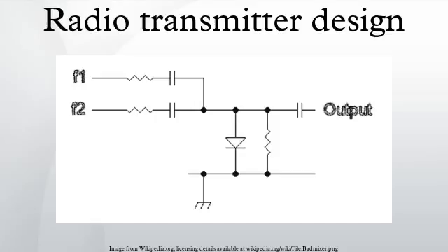Digital modes. Transmission of digital data is becoming more and more important. Digital information can be transmitted by AM and FM modulation, but often digital modulation consists of complex forms of modulation using aspects of both AM and FM. COFDM is used for DRM broadcasts. The transmitted signal consists of multiple carriers each modulated in both amplitude and phase. This allows very high bit rates and makes very efficient use of bandwidth.